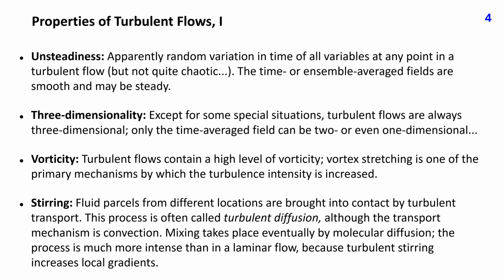Except for some special situations, turbulent flows are always three-dimensional. Only the time average field can be two or even one-dimensional. Turbulent flows contain a high level of vorticity. Vortex stretching is one of the primary mechanisms by which the turbulence intensity is increased.